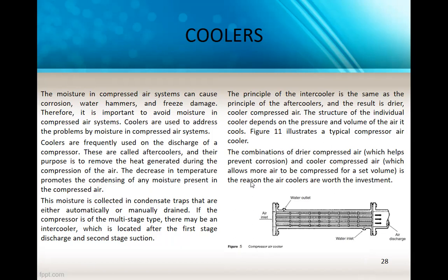The combination of drier, compressed air, which helps prevent corrosion, and cooler, compressed air, which allows more air to be compressed for a set volume, is the reason the air coolers are worth the investment.